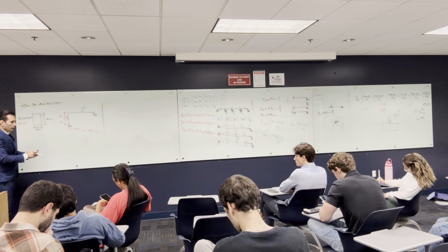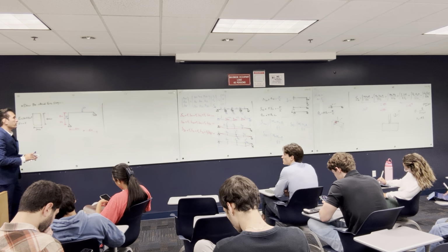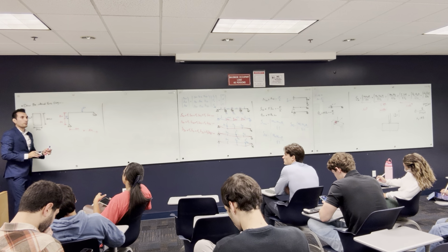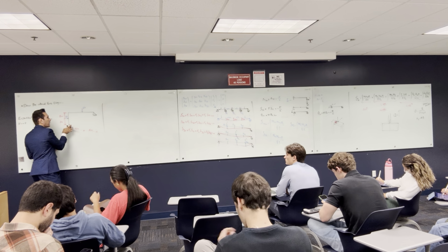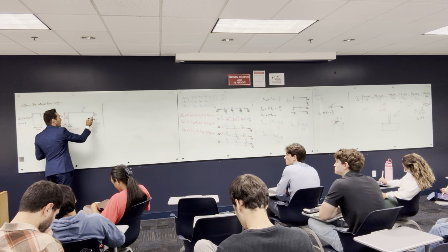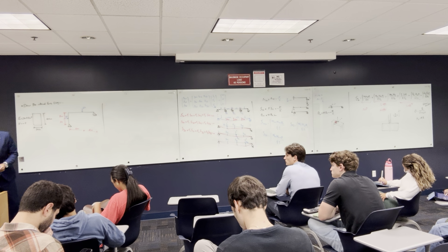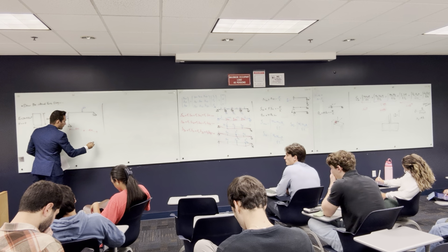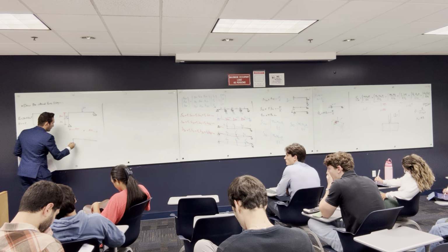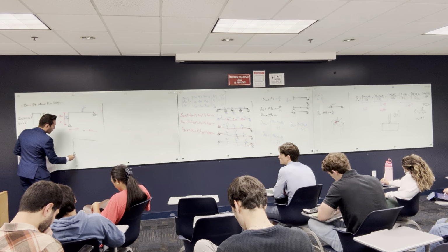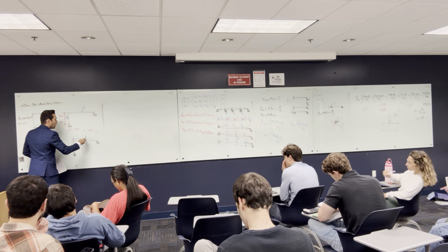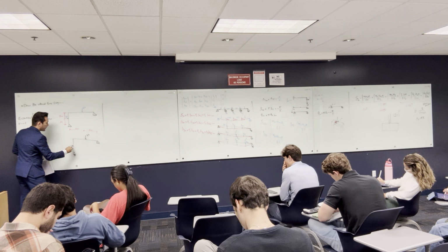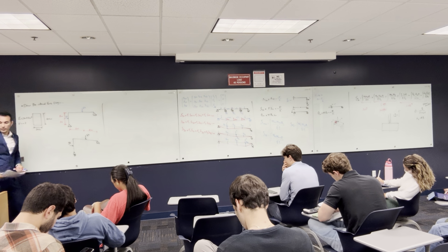So the thing is, to solve this problem, I told you you have to choose a main system without the redundant. This can be redundant, or this one can be redundant, like the Y reaction here. So what I did here, I picked this system with a roller here and a hinge here. That is my main system, and I put the original loads, the 6 ton and the 3 ton. First you have to solve this main system.